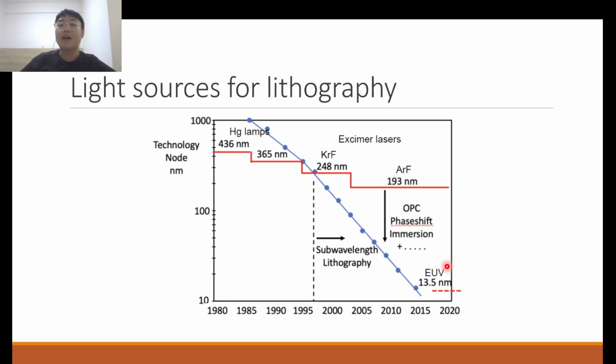However, after that, the company ASML developed what is known as EUV, extreme ultraviolet. Why extreme? Because it's an extremely small wavelength of only 13.5 nanometers. And there's a very special and difficult to master light source that is driving these EUV light sources.